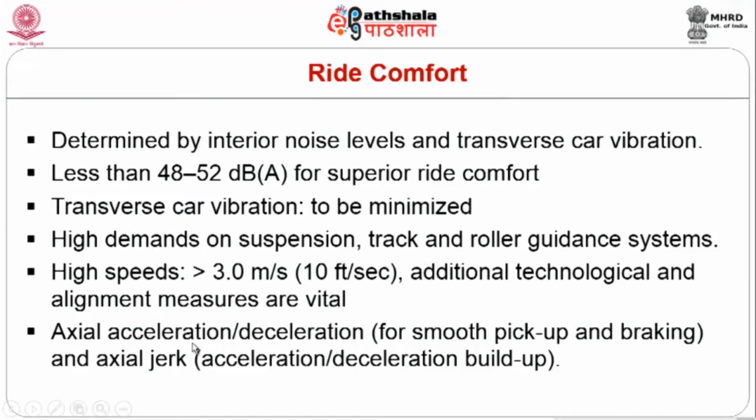Axial acceleration and deceleration are very important, and need to be very smooth in terms of picking up speed and in terms of the braking system to bring down the speed. When the elevator car stops at a particular floor, the jerk factor also has to be taken into account, and we need to bring in an almost smooth landing experience for the occupant within the car.